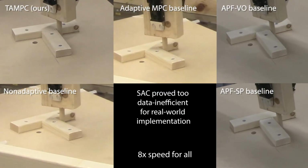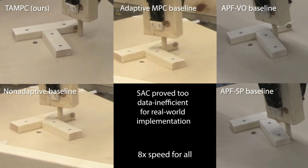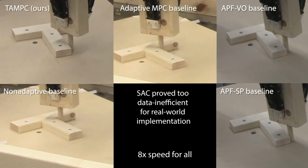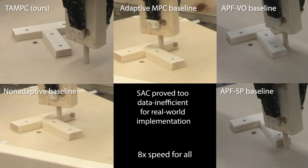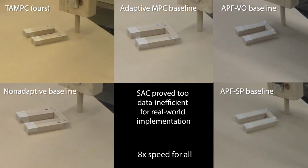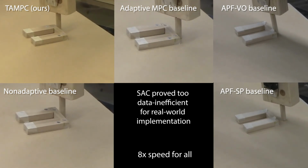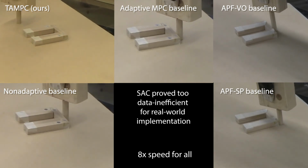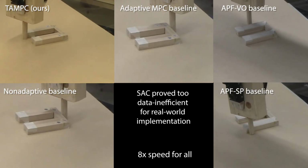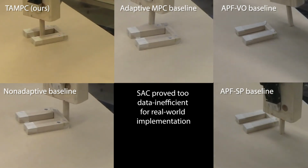On the peg tasks, our trap set is critical for avoiding previously seen traps. One challenge of this task is that the goal is next to a trap. The repulsion from the trap set and the attraction of the goal induces a potential field that could have many local minima. To address this, we anneal the trap set weight when in nominal dynamics. Note that most of the parameters use the same value across environments and tasks, demonstrating the robustness of our method. See the paper for how to independently tune some parameters to improve performance.